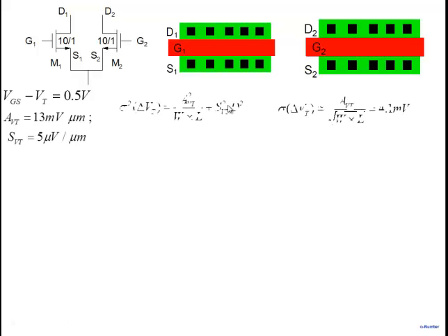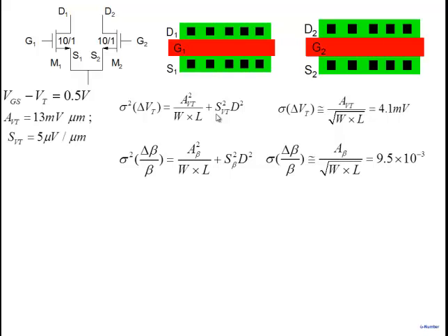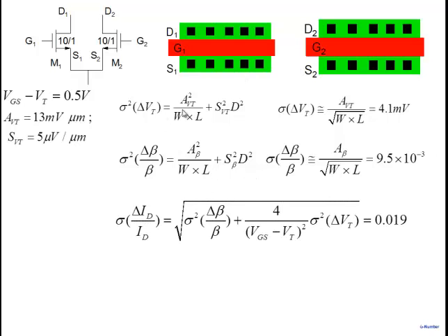Okay. All right. So this is what we had discussed earlier. Say I have a differential pair, two transistors M1 and M2. The usual way, or a simple way, in which I would fabricate is to make one transistor here, make another transistor here, then you connect S1 and S2. So this would be a normal way, but what would happen is, I can calculate the sigma square, and for a moment, not talking about D, just taking the first term. Because I don't have right now the value of D, it depends on the layout, and from there we'll have to figure it out.